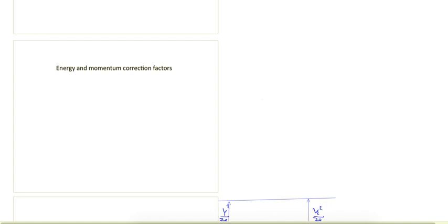As we know, whenever we are solving any equation, we take the average velocity, and so we bring some error in this. If the variation is more in the channel, like this cross section, we know that velocity cannot be the same at every point because there will be friction near the boundaries, so velocity will be less near the boundaries and more near the center portion.